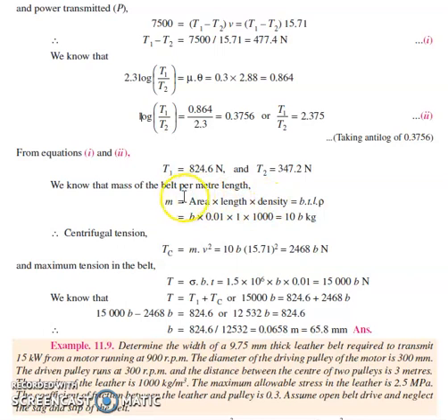Density is equal to mass by volume, and mass is equal to density into volume. Volume is area into length, so mass is density into breadth into thickness into length L. Density is given as 1000 kilogram per meter cube. Substituting all the known values, we don't know what the breadth is, but the thickness they have given is 0.01. We need to write everything in terms of meter, because we have taken the density in kilogram per meter cube. All values should be in meter, and mass is 10 times the breadth, in kg.